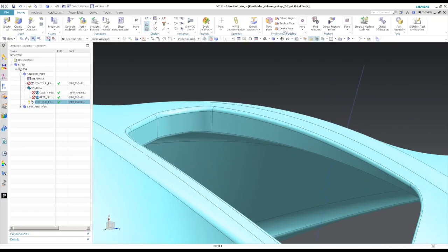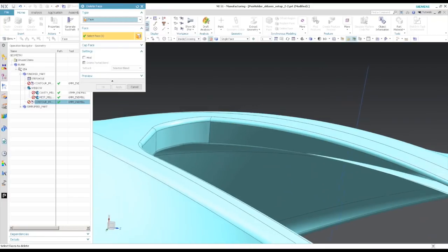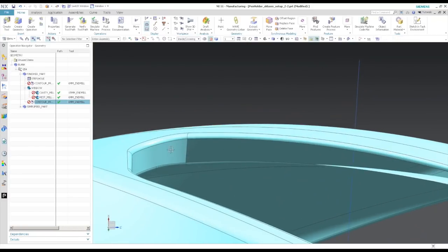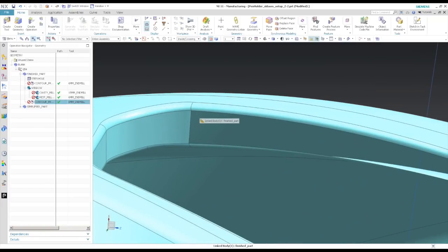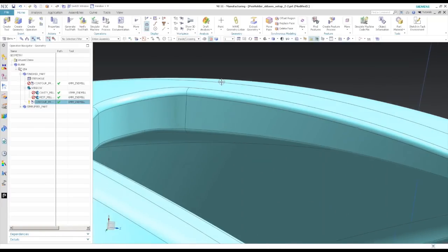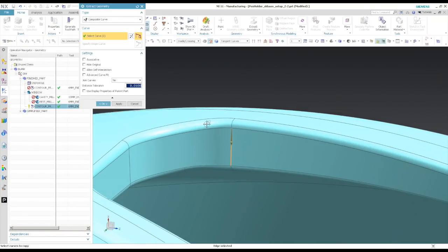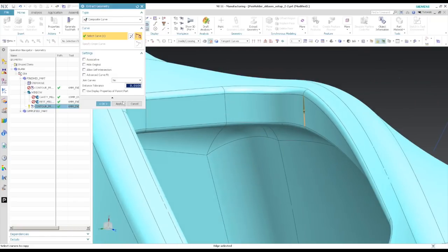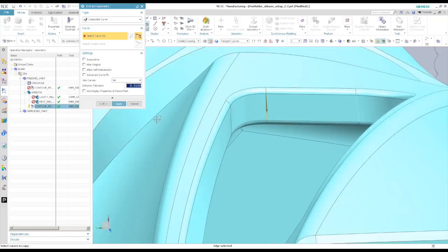That was one of the mistakes I made. So if you're deleting this face, patch it before deleting this one, or you can extract these curves so that you have them there in order to recreate similar face geometry as to what was there.